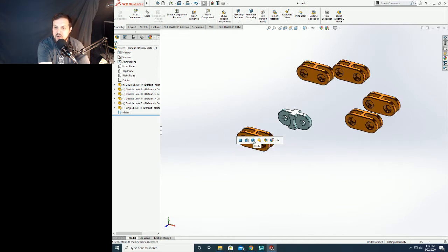When I let go, you can see it's going to bring up a prompt window or a quick prompt toolbar. It's going to give me a bunch of different options. So I can go to Face Extrude, which is just that face that I dropped it on. Go here, Extrude 1, which was the original extrude that we did to create the part. I can go here with the body, and notice this is changing them for all of them. This is actually affecting the part itself.